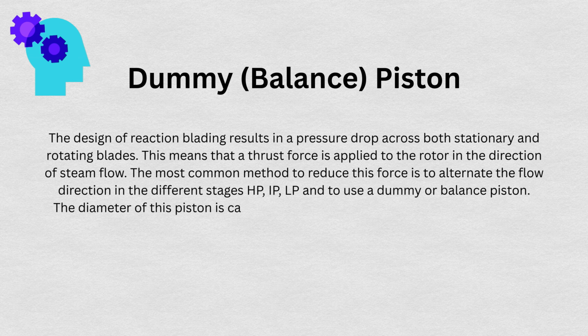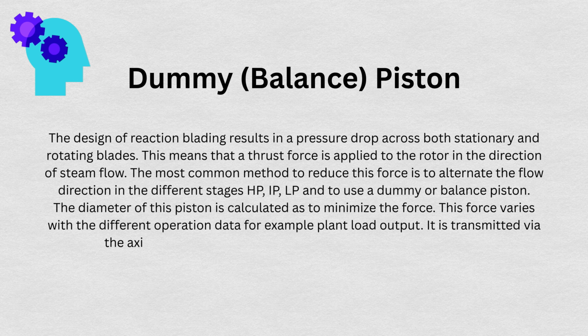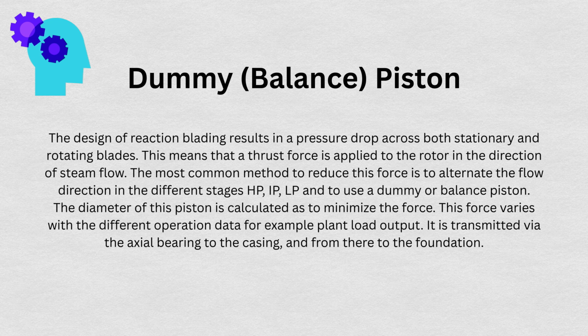The diameter of this piston is calculated to minimize the force. This force varies with the different operation data, for example plant load output. It is transmitted via the axial bearing to the casing, and from there to the foundation.